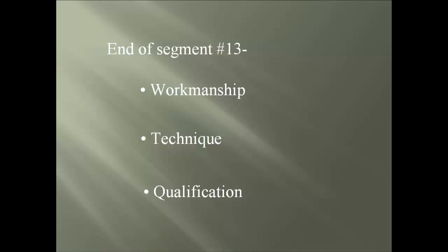And lastly, we covered the observation of welding reinforcing steel by mentioning the items that the contractor must accomplish and provide for compliance with the code, like the WPS and welder qualifications. Plus, we covered destructive testing, the joint types used for certification, while pointing out that both the quality control and quality assurance professionals should have both training and actual field experience, plus any proper certification to perform the duties that will enhance the project.